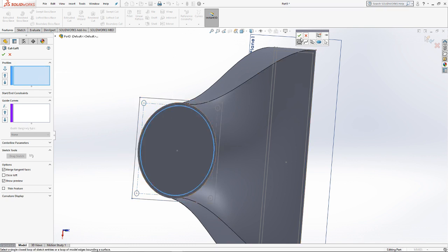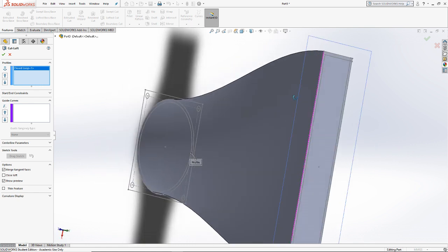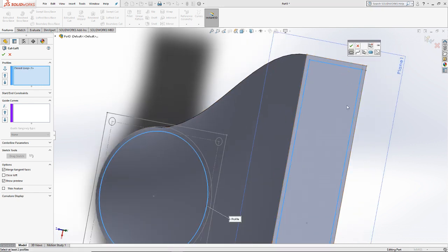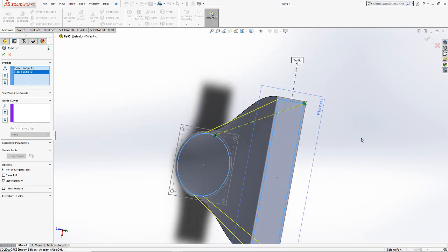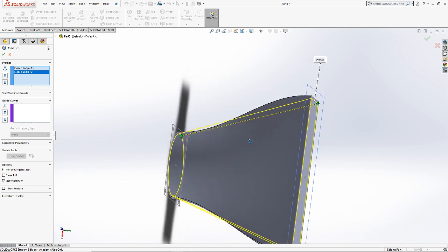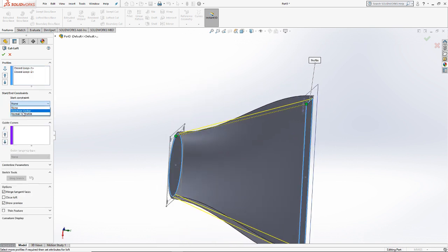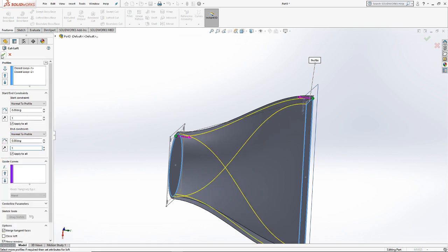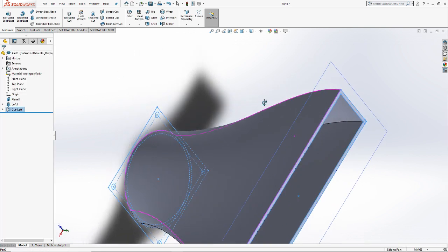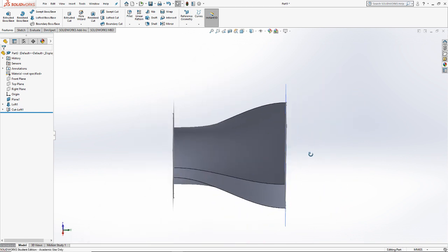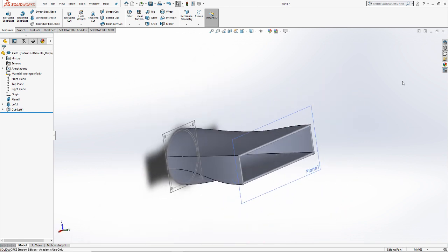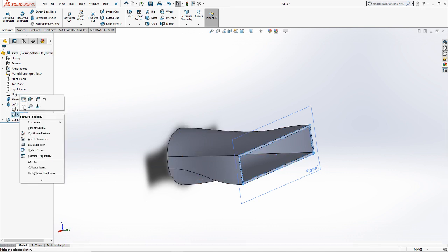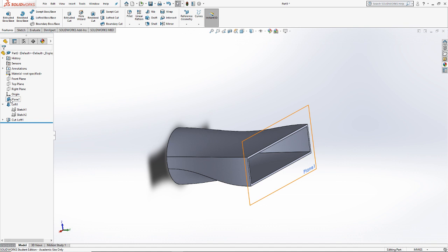And then in order to be able to grab just that center circle, a lesson that we learned very painfully about 2 minutes ago, and select my 2 inside edges, then I apply the same constraints as earlier, we come up with the same geometry, just spaced 2.5 millimeters away. Now I can go back and hide these again if I wanted to. Make it a little bit prettier. I could hide the plane too if I didn't want to see that.